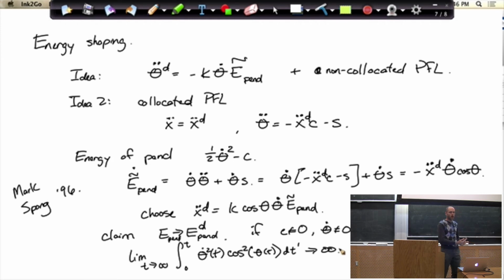So, for instance, Jean-Jacques Slotine, who's in mechanical engineering, has a hugely powerful result about adaptive control for nonlinear manipulators. If you have a trajectory, even if you have unknown parameters of your robot arm, for instance, and you have a desired trajectory, you can adapt your estimate of the parameters and the controller at the same time and guarantee that you're going to get to your desired trajectory.